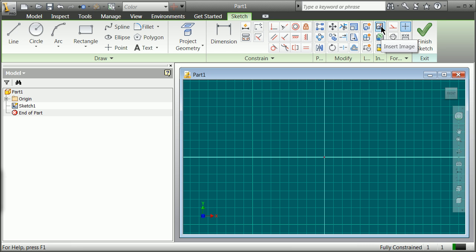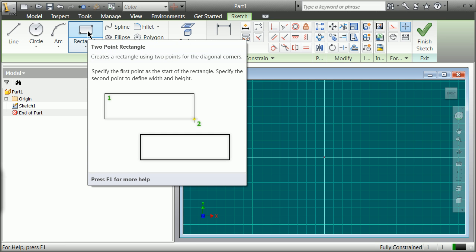You could have done a picture out of the book for some of these problems, but it wouldn't necessarily be to scale. So if you remember our general layout, I'm going to do one, and then I'm going to go into an assembly and show you how you can go about and project geometry from an assembly and go ahead and draft right on top. So I'm going to assume a 20 foot for this case, so I'm going to do a 120 inch by a 12 inch.